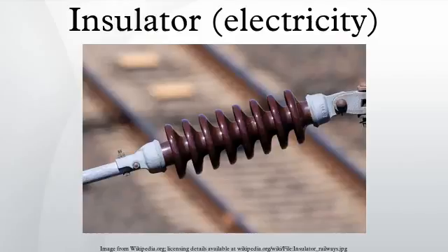History: the first electrical systems to make use of insulators were telegraph lines. Direct attachment of wires to wooden poles was found to give very poor results, especially during damp weather. The first glass insulators used in large quantities had an unthreaded pinhole. These pieces of glass were positioned on a tapered wooden pin, vertically extending upwards from the pole's cross-arm. Natural contraction and expansion of the wires tied to these threadless insulators resulted in insulators unseating from their pins, requiring